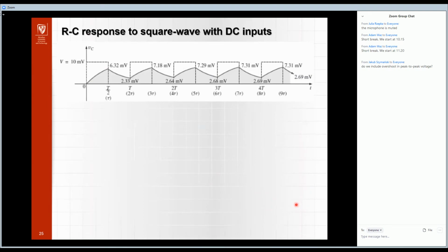Okay, and now I sketch all these signals. So now we calculate amplitude in this case. Now we try to calculate for this region from half t to 1t. So this is the discharge phase between this time and this time, and now we should switch the initial and final value, because for us the final value from the previous is the initial, and we assume that we have here the zero voltage, and we can calculate the voltage at this point t.